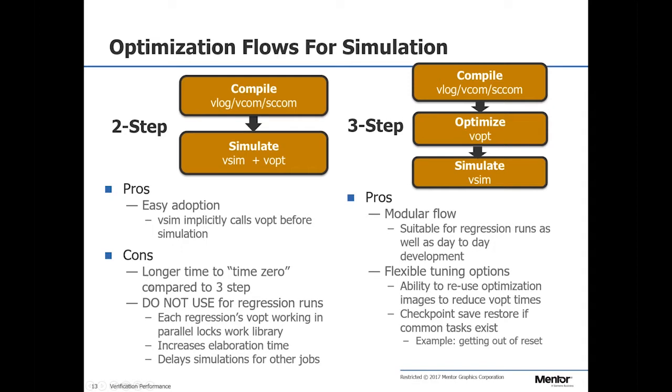It does take a little bit longer to go from, I said, vsim to that time zero where the design is loaded up, but you haven't run any simulation yet. And it can be bad for regression runs, because every time you run the simulation, it's going to do a vopt. And maybe you only need to do that vopt once.